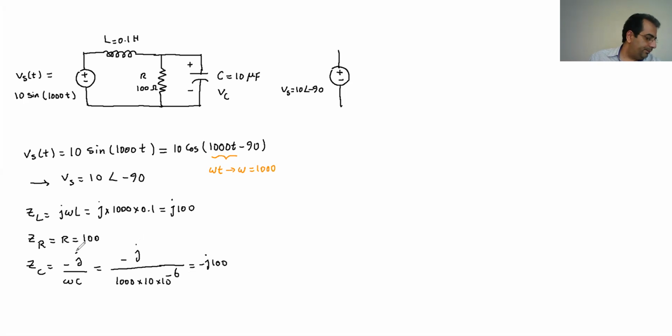So now we have them in this form. Also, if you want for the phasor, because usually we are going to need the angular format as well. We know that ZL is omega L with angle of 90, so you can convert that to, if you do the calculation, 100 with 90 degrees.